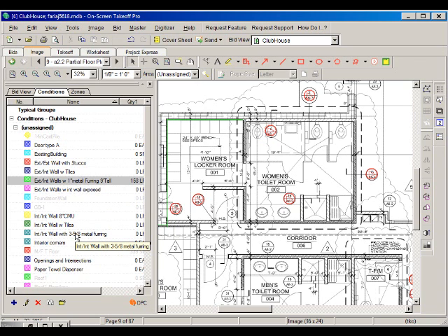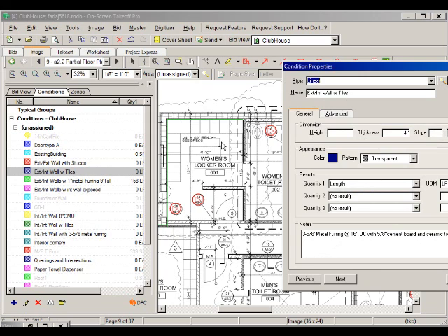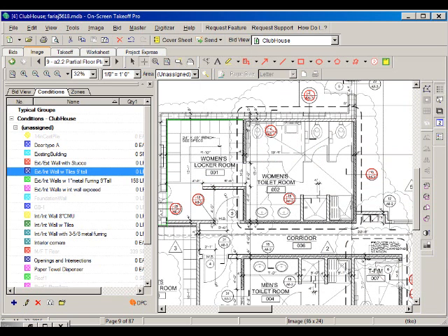So this will be exterior interior wall with tiles. This one here. This has 3/8 metal furring at 16 inches on center with 5/8 cement board. Perfect. And these are 9 feet tall. So we enter the height as 9 feet. And then we set the thickness to 4 because we have 3/8 plus the drywall, so that's going to be almost 4 inches.